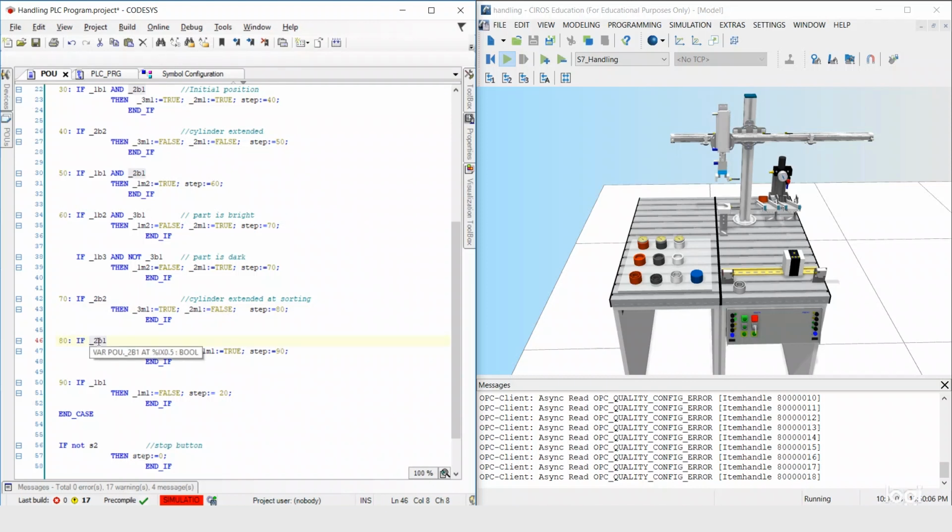So you can see that this is actually a step-by-step approach, which is unimaginable in ladder logic. This can only be achieved with two programming languages, or rather three. This can be done with structured text, it can be done with sequential function chart, and also it can be done with statement list. I'm not saying that you cannot absolutely do it in ladder. What I'm saying is that it becomes very difficult to do it in ladder, because ladder does not have a step sequence like this. So you have to use a lot of flags, a lot of relays for that.